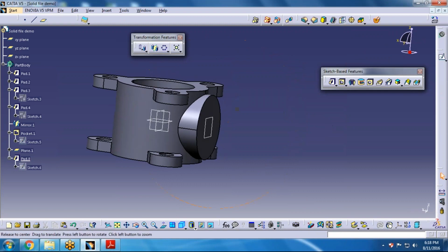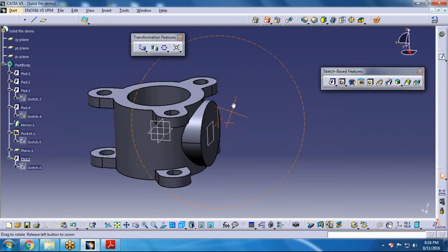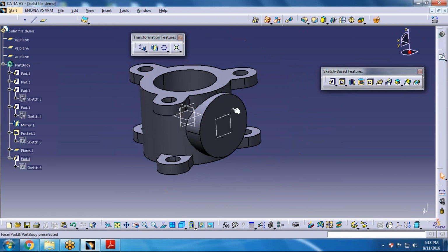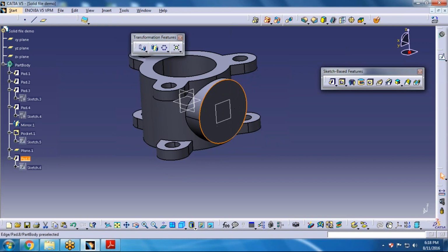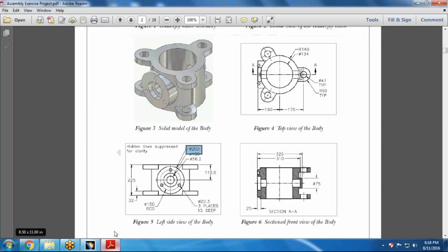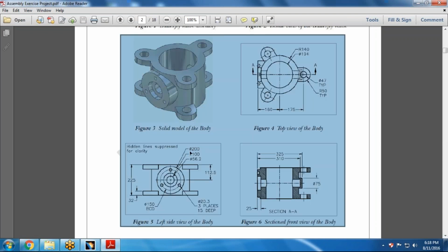Now we have got the geometry up to the next surface. That is a topic in extrusion. I will discuss this, but in class only, right? So right now I'm just going to create what you can see there. They have shown us that there is a pocket, a smaller pocket inside there. Before starting with that, I'm just going to create one circle of around 100 millimeter.